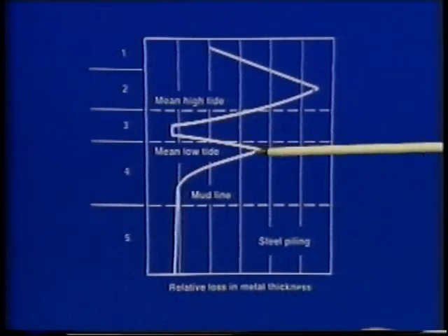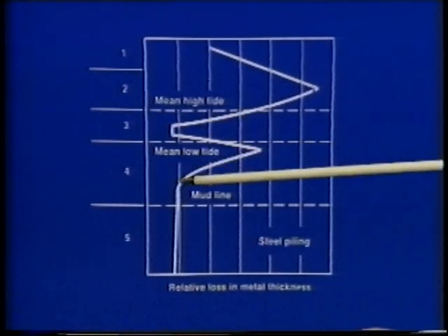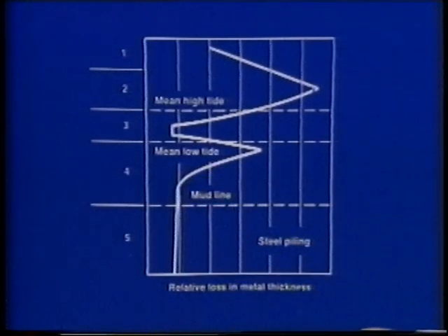As we get down in a totally immersed area, we find the corrosion rate dropping, and down in the mud line, it's down even lower. This data was reported in a Metals and Ceramics Information Center report on the corrosion behavior of metals in seawater.